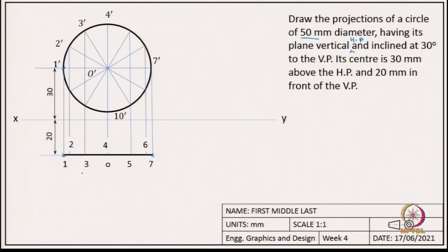The reason why we are looking at these 12 points is, we will trace these 12 points from the circle to the ellipse. Then it becomes easy for us to draw the ellipse, because we just need to connect those 12 points to draw something looking close to an ellipse.